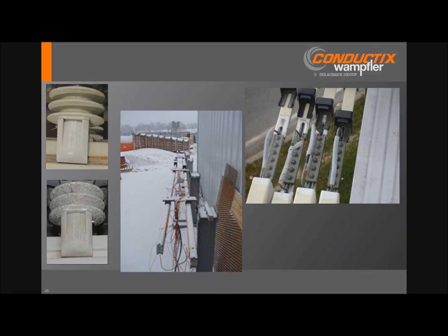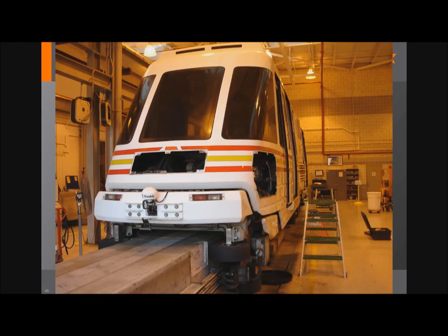The idea here is that these are to be turned on before the environment reaches freezing temperatures to prevent the formation of ice. It takes a considerable amount of power to de-ice, particularly these conductor systems with such a high ratio of surface to cross-sectional area. I mentioned lateral orientation, kind of hard to see. This is Jacksonville Monorail, but the conductors, this is an AC system, are side-mounted, and these are essentially exposed to the weather, and every time it rains, the shoe wear definitely goes up.